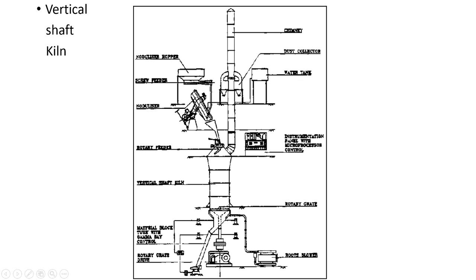Starting from the top, at different temperatures, different types of reactions are taking place. The whole kiln charge, composed of nodules and clinkers, rests on a specially designed flat grate rotating slowly at the bottom of the kiln, mounted over the kiln shaft. When this is rotating, after the product gets distributed using this rotatory grate, it continuously rotates.